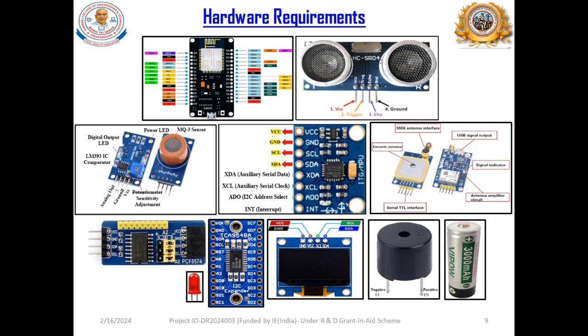It has only 9 pins for the specific digital IO read pins. So we need a GPIO pin expander module. So we use the 8 pin expander module PCF8574. And the next one is TCA9548A.